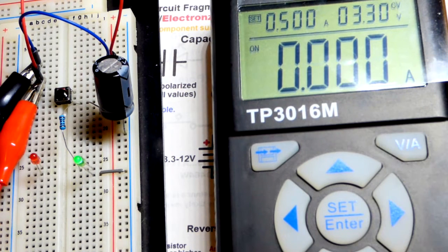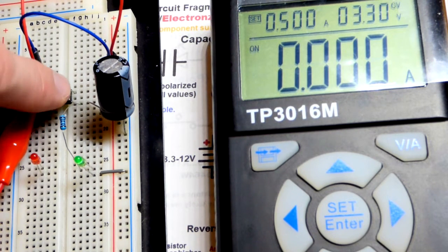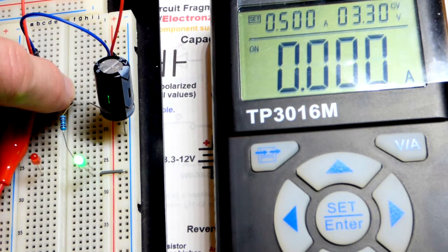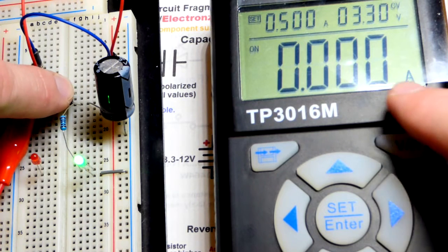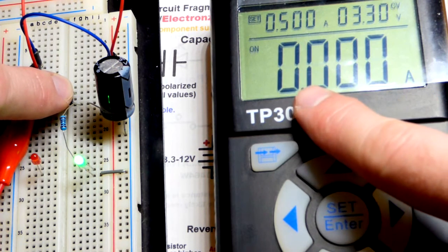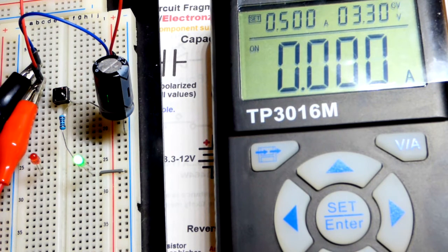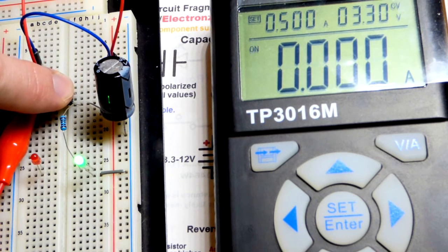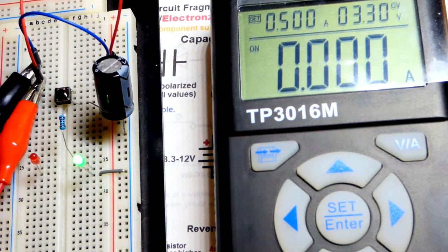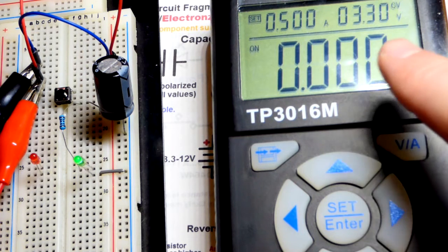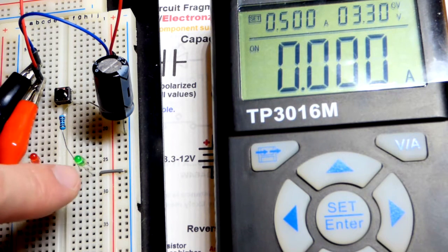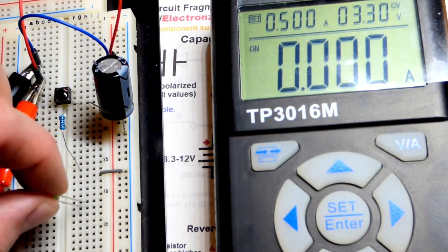Also, we can look at the current being demanded from the power supply. Right there, it's not showing anything, so the current is very, very low. It may be below 1 milliamp. So that's 1 milliamp, 10, 100, and then 1,000 if there were ones there. But in any case, you can see as soon as I let go of the button, the capacitor built up a charge instantly. So in this case, we get an instant charge, but the discharge takes time. There's a changing voltage right now. It's dropping. We're only dealing with 3.3 volts, the LED blocks almost 3 volts, and so we're dealing with very little current.